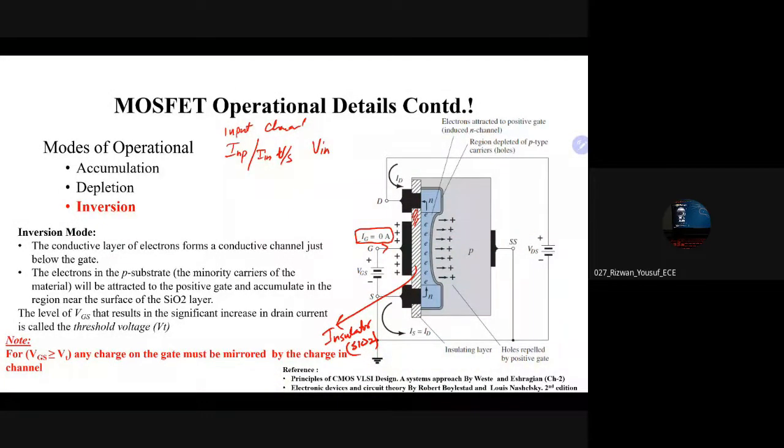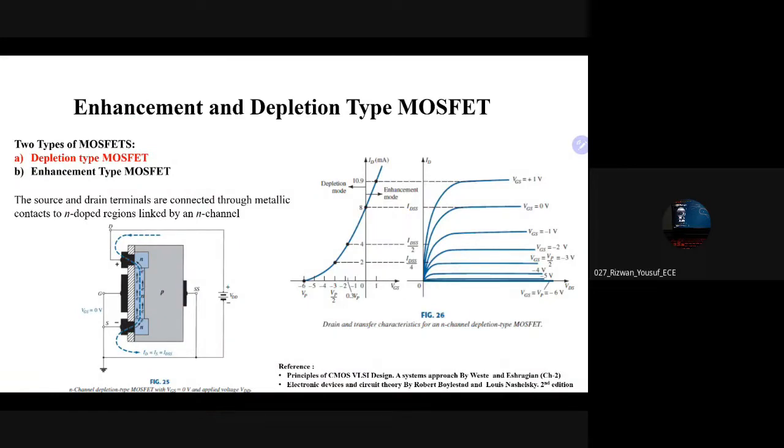यहाँ जो ग्राफ बनता है, यहाँ बनता है ट्रांसफर characteristics का. उसमें हमेशा ID is the output current. Okay, तो input voltage होती है VGS versus output current ID. So it is always like this, VGS versus ID. तो इसमें input characteristics नहीं होती है, because IG is eventually 0 because there is an insulator there. Now see, these are different VI characteristics or transfer characteristics of devices.